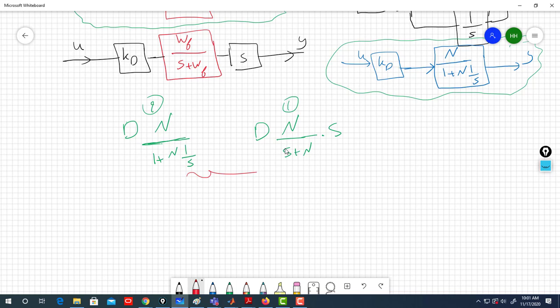So here I'll tell you, actually yes, they are the same, but this one is easy to read and understand. You have the derivative term Ds times the filter. Directly I can say, okay, this is the derivative term: the derivative constant of proportionality times the derivative s and my filter. So it's easy to read and understand, but it needs more math operations and memory to accomplish.